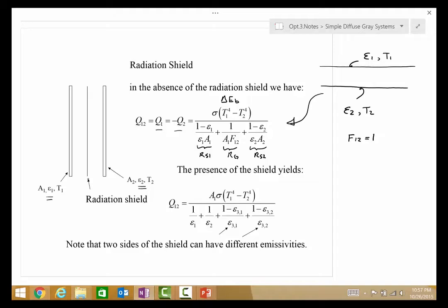And so in specifying a problem of that type, what we have is a problem where, and this is condensed, we might think about it in the more fully fleshed out version as having geometric resistances on our primary surfaces, view factor to our primary surface. I'm going to say this is 1 over 1. I hope you recognize why it might be confusing. So let's just do this. The areas are all the same. So we have A here. F1 to the shield is 1.